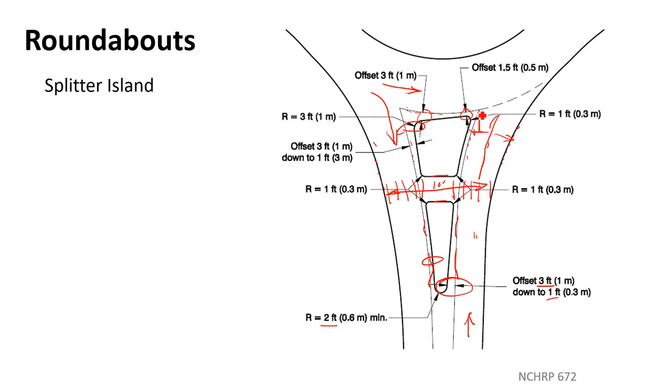And then from that, whether you're doing the edge of pavement design first or this path first, you're going to offset and find this inside line for the vehicles, your travel lane through there. And same on this exit, you're going to eventually work out until you find this line. Once you know where those two lines are and the circulatory roadway line, then you start building your island inside of that. And so that's the workflow when you're doing these island designs. Typically you start from the outside, then you work your way in.